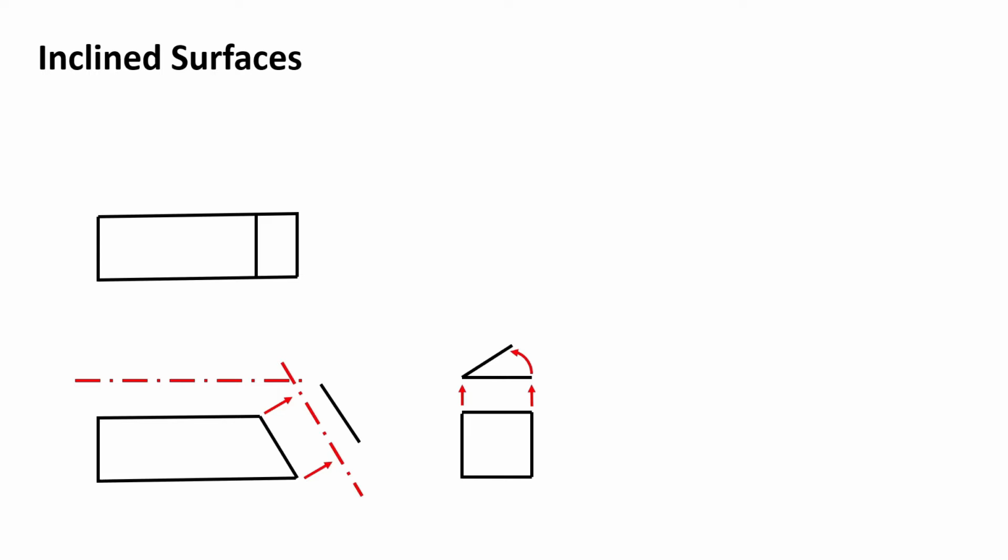Next, draw the line in its proper position. Duplicate this line now in position on the auxiliary view. And finally, draw the last side parallel to the first line that was drawn.